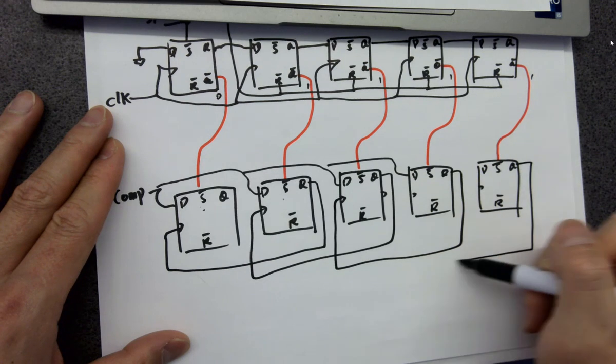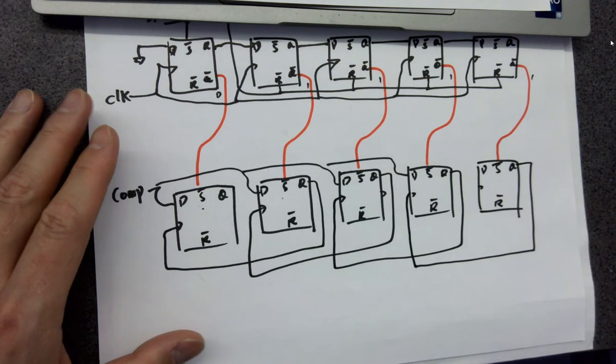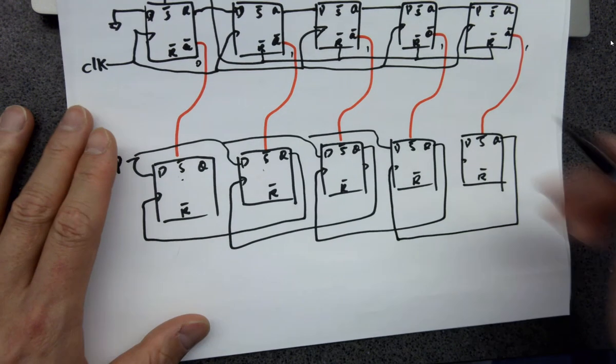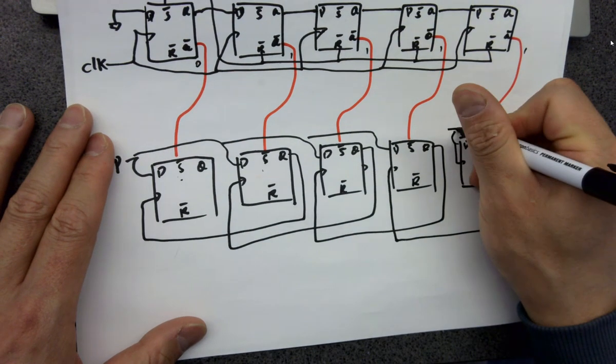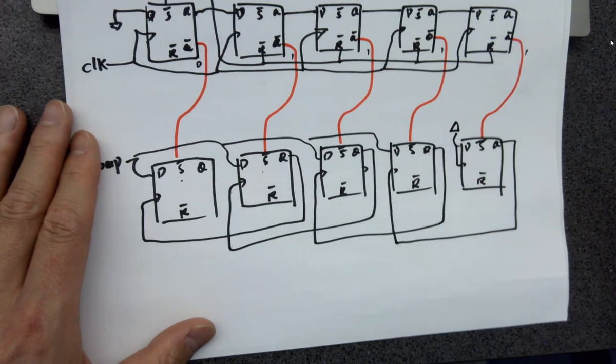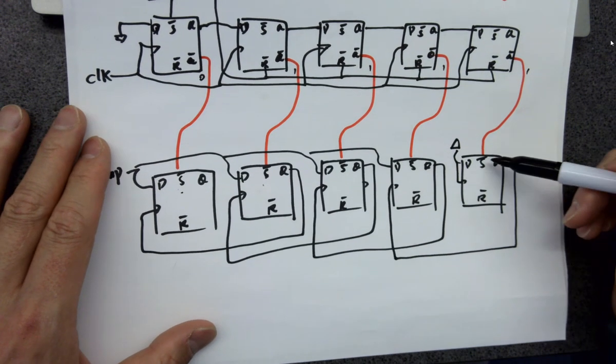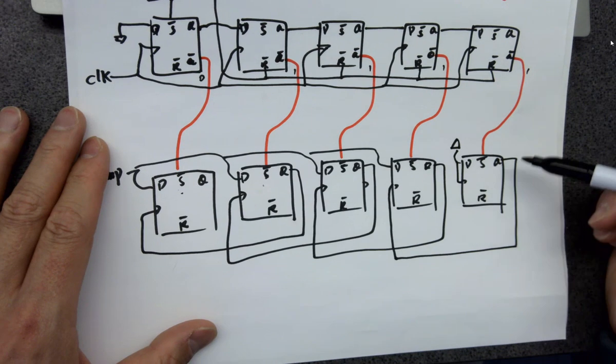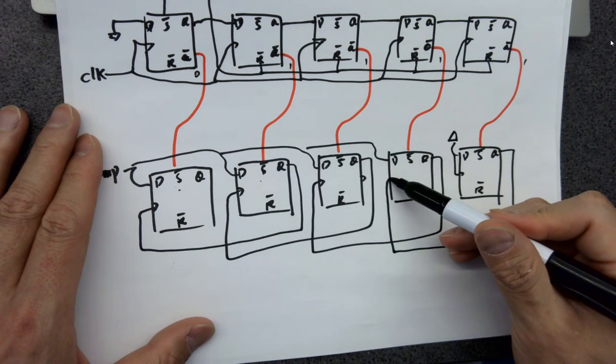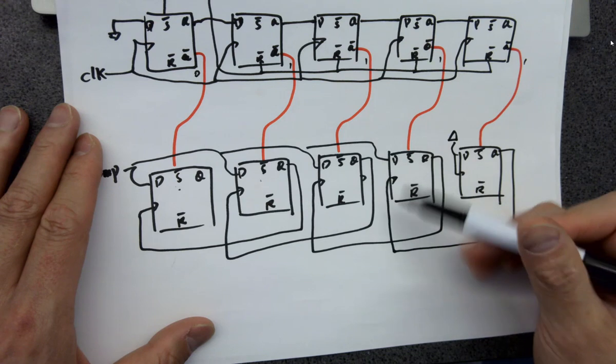And the Q of the next stage is used as a clock from the previous stage. So this one doesn't matter, you can ground it. It's okay. So this one is just receiving a Q naught signal to set everything and then provide a rising edge for this stage over here in front of it.